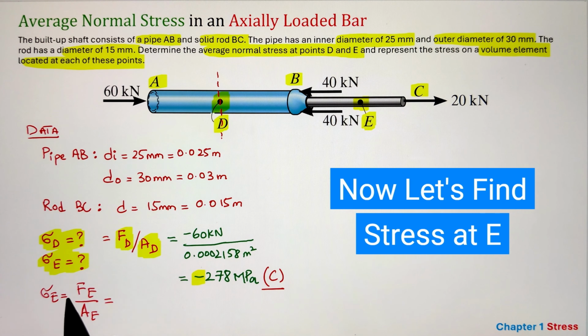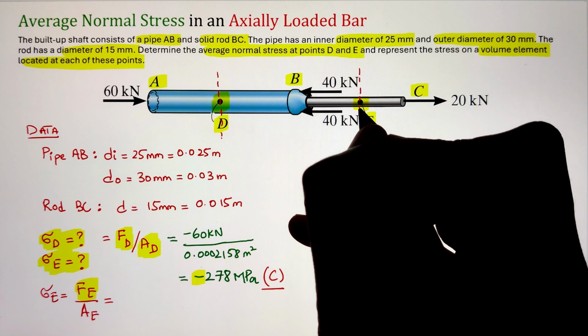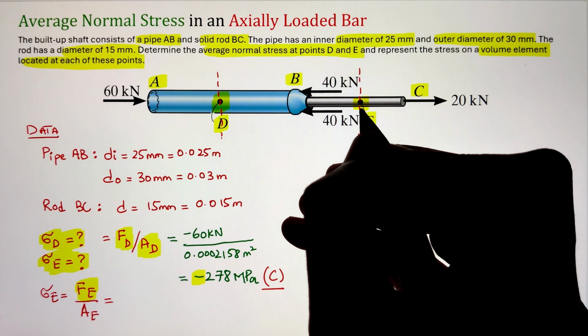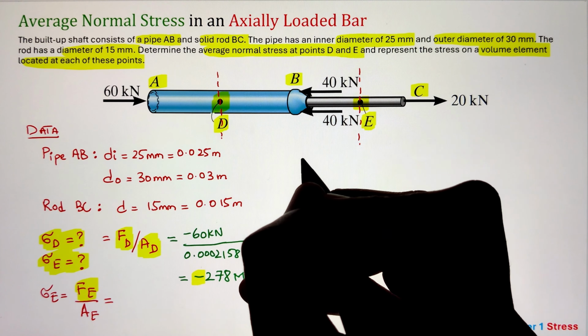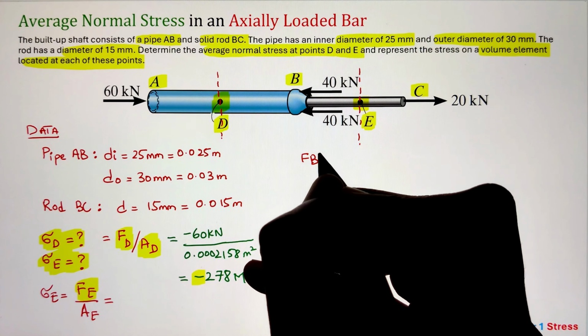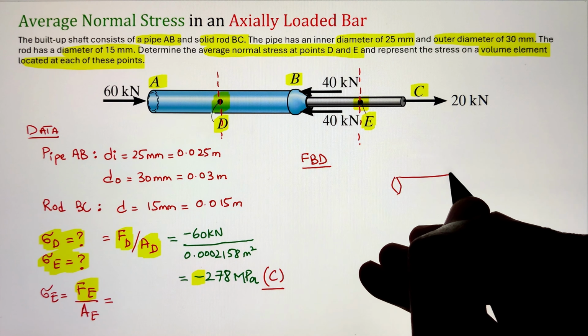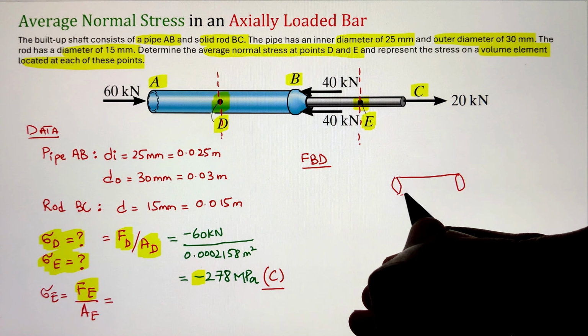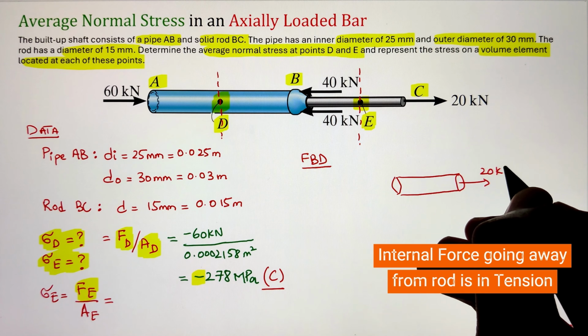So to calculate the force at point E, again, we have to utilize our method of sections. Let's create a cut at point E and separate the two halves. Now, in this case, again, I can select either a section from E to C or from E to A. Since from E to C I just have one force, it will be way simpler to solve this.